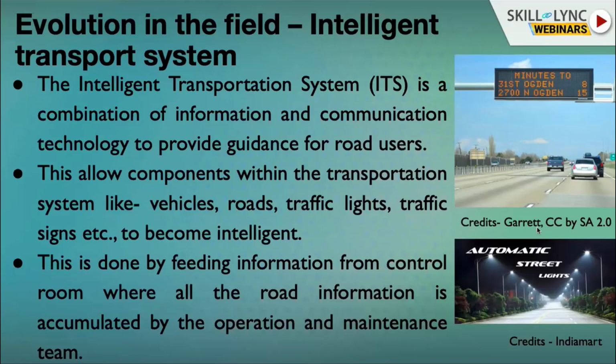How can automatic axle load measurement be done? This is usually done through a weigh-in-motion system. This is a technology in which the vehicle can travel at a higher speed, even at 80 km per hour, but still the vehicle axle load can be measured to an accuracy of 90%.